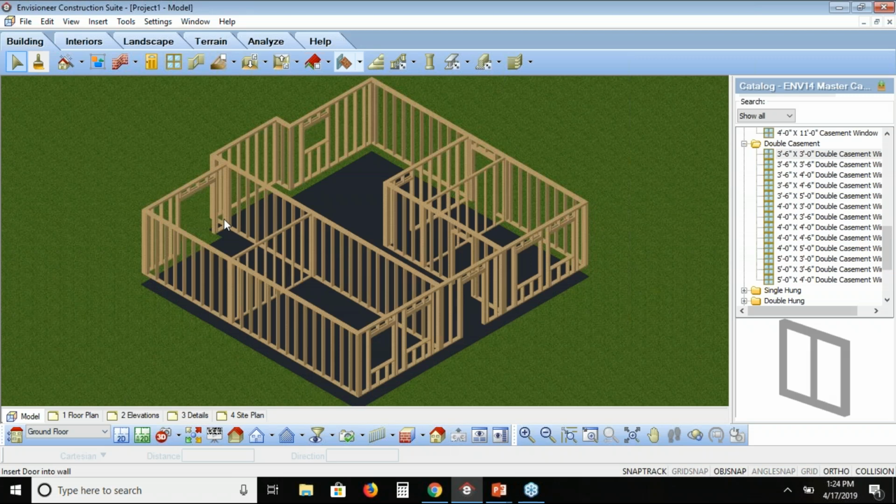Is there anything I'm forgetting? Taking a double look at your PDF or any framing diagrams that came through, or header tables. Perhaps you're deviating from the span tables that are there because, for whatever reason, there's a point load coming on top of this front door, and you need to beef up that header. The plans call for it. It's an LVL header over top of that door. How do I change just that one opening, where everything else I want to follow that span table?